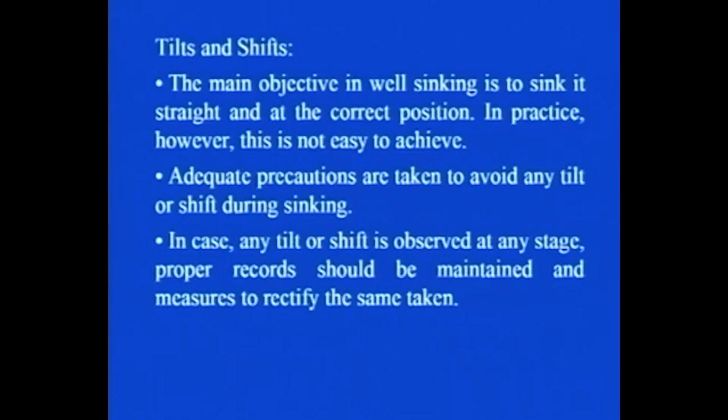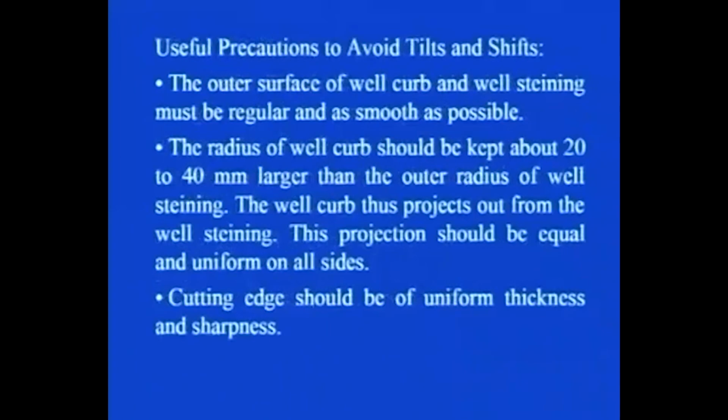Then tilts and shifts. Now coming to the tilts and shifts, some of the aspects related to these. The main objective in well sinking is to sink it straight and at the correct position. However, in practice it is not easy to achieve. So adequate precautions are taken to avoid any tilt or shift during sinking. In case any tilt or shift is observed at any stage, proper record should be maintained and measures to rectify the same are taken at that particular instance only.